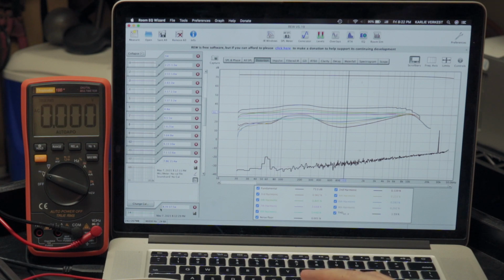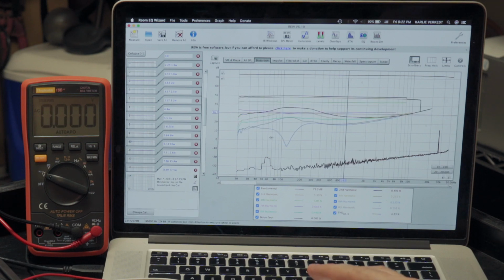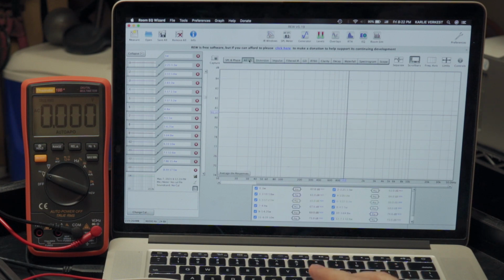And here we went 1 decibel more, 17.5 watts. And you can see our distortion is beyond, it's like 6.32% total harmonic distortion here, and it's almost all third. You can see the third is up here, pretty constant across there, and all these other distortions creeping up as well. And we can also look at these SPL numbers here.